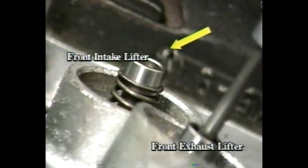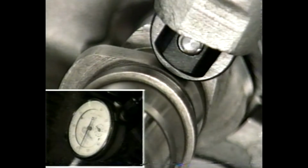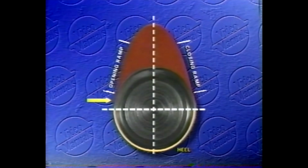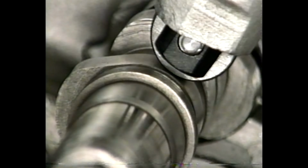Now we take our lifter over the cam lobe to the heel or base circle of our cam. It is here that we must zero the dial indicator on our lifter. Once zeroed, we continue to slowly rotate the crankshaft until we find exactly where the cam lobe ramp begins, as shown on this diagram. The cam lobe ramp begins and the base circle ends when the dial indicator starts to move off zero.